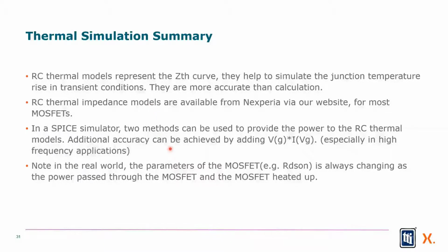In the SPICE simulator, you just go ahead and set it up, as we've shown you with RC equivalents. If you want to get fancy on it, you can also add in the gate voltage and the gate current, because that actually is pumping energy into it. That gate control adds a bit more power into the MOSFET. So if you really want to know everything, you might want to add that in. In most cases, it's insignificant, but it's an option that you might want to put into it.